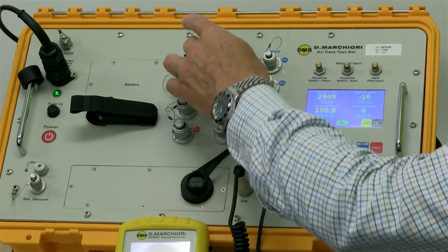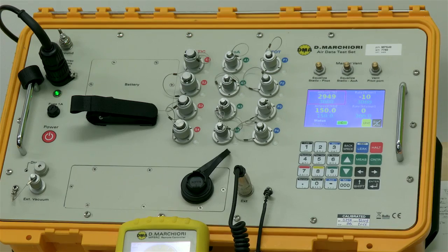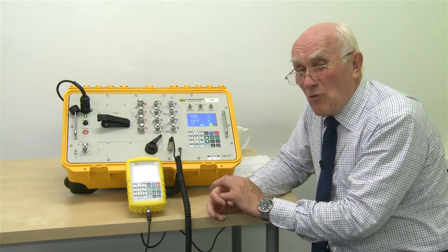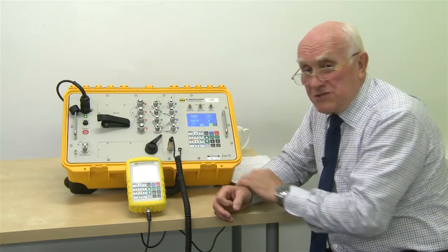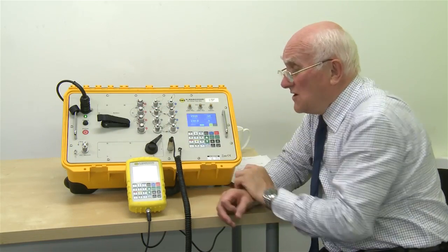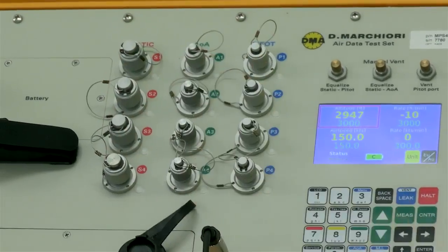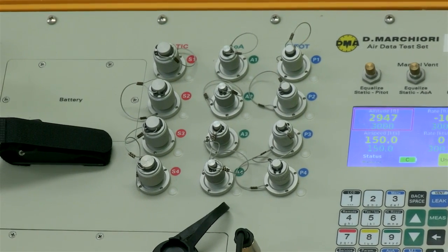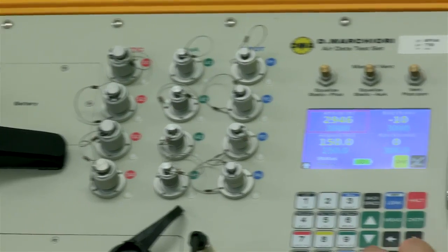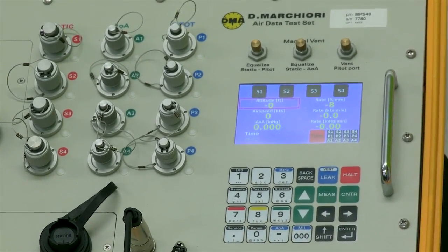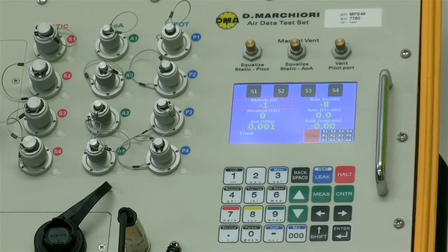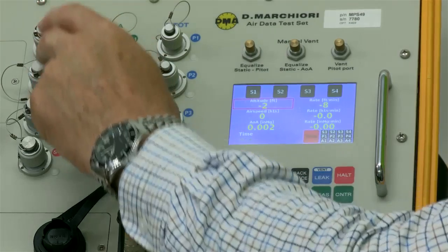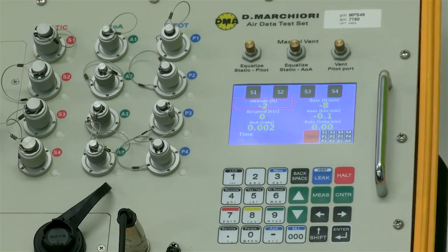People like to be able to then examine what is happening across the whole range and indeed find out where the leak is, if there is a leak. And to do that, we have the multiple isolator, and that's what these are. We have the ability to isolate any one of those to find out which is leaking. To do that, we go to the Shift key and the multiple isolator. And that screen then shows us, just as it did in the other full measurement mode of the leak, the ability to select each one of these and switch it off, close it.